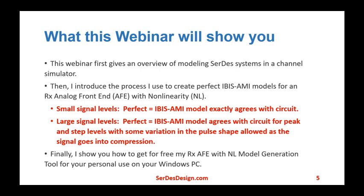At small signal levels, perfect means that the IBIS-AMI model output waveform exactly agrees with the circuit output waveform. At large signal levels, perfect means that the IBIS-AMI model output agrees with the circuit output for peak and step levels, and with some variation in the pulse shape allowed as the signal goes into compression. Finally, I show you how you can get a copy of my receiver AFE with nonlinearity model generation tool for use on your Windows PC.